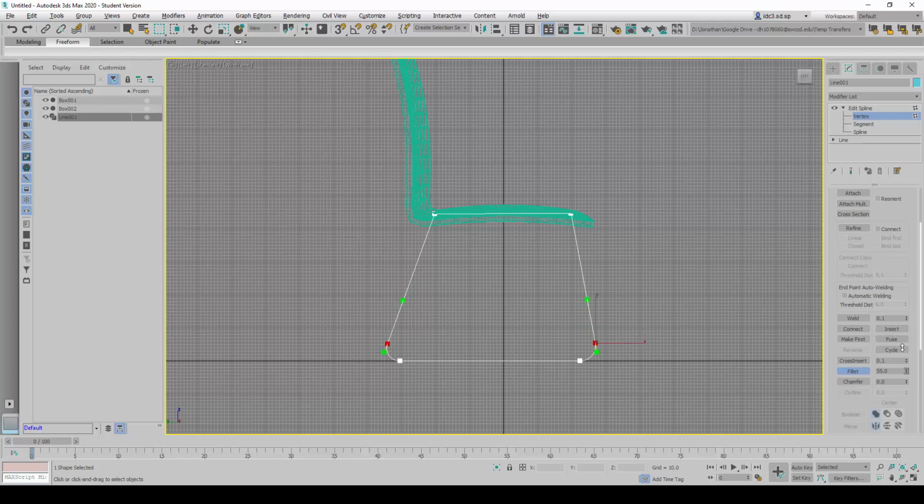By doing this, the numbers will be shown here. Notice when I drag up, the number increases, so we can roughly gauge and establish a certain number that will look nice enough to form the fillet radius. Just to make the numbers look good, I'm going to undo this now and use the 50 number here, so it looks something like this.